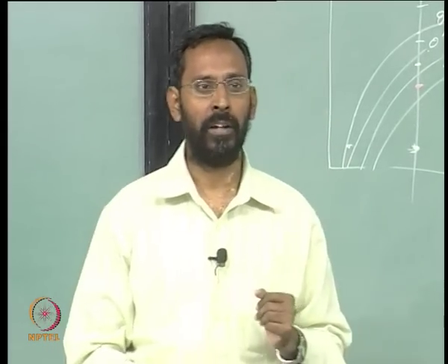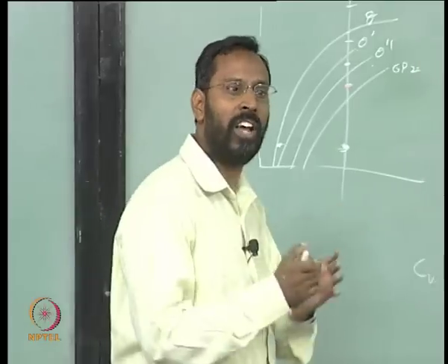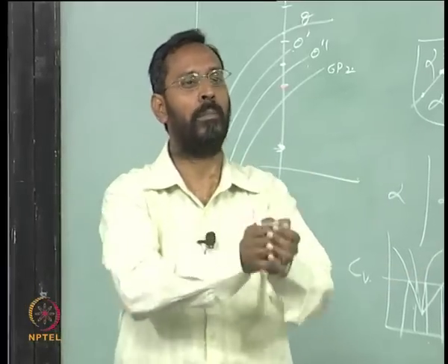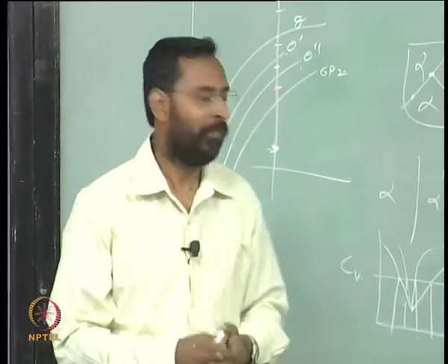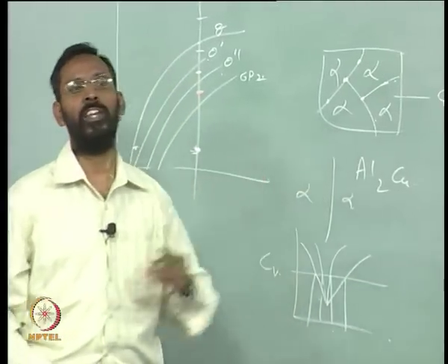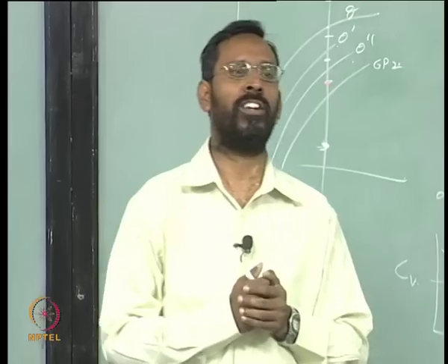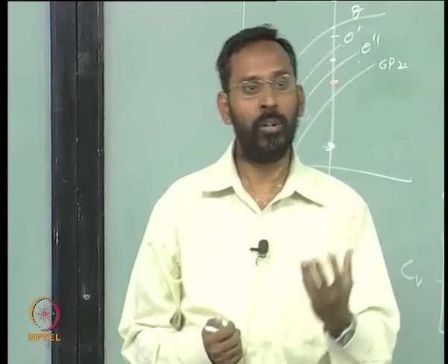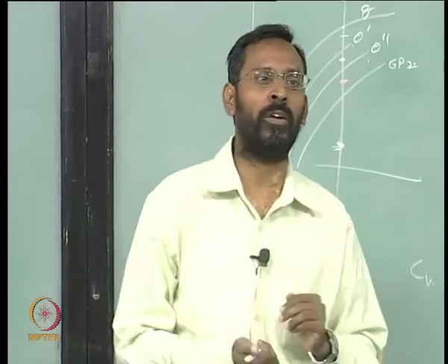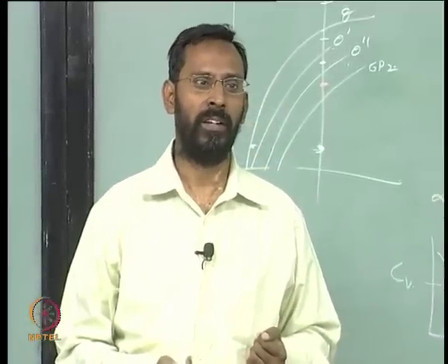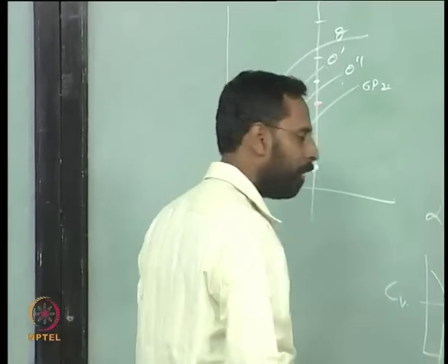R star is important. So pure copper of a critical size has to form, which means you need to have sufficient vacancies where copper atoms can come and occupy. If you do not have them, then you will not see any nucleation. Then the only other possibility is that nucleation occurs on certain crystallographic planes. If it is nucleation on the vacancies, there are no crystallographic planes, and it can again be random nucleation. Is it clear?